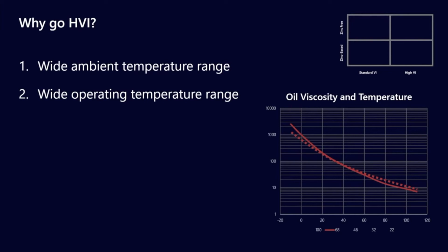So as you reduce the size but put more power through the pack, that's going to mean more heat. And that's just part and parcel of the designing of the system. So as all the hydraulic packs get smaller and smaller, we tend to see higher temperatures, and that's really driving a lot of lubricants to go to a high viscosity index.